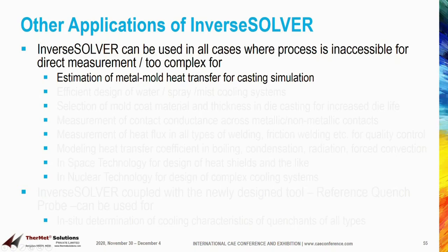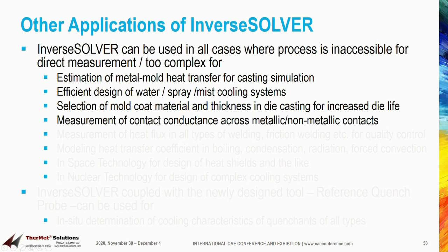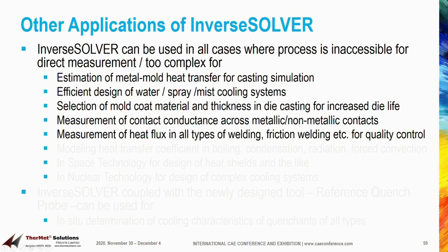Inverse solver can be used in all cases where process is inaccessible for direct measurement, for the estimation of metal mold heat transfer for casting simulation, efficient design of water or spray cooling systems, selection of mold coat material and thickness in die casting for increased die life, measurement of contact conductance across metallic or non-metallic contacts, measurement of heat flux in all types of welding, friction welding, etc.